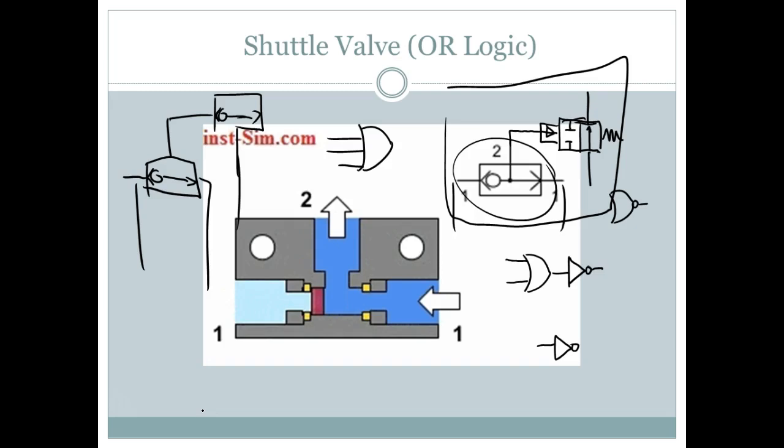No, the flow control is at the cylinder. So if you're going to control the speed of the cylinder, then you would control it at the cylinder. You wouldn't control it at the valve that's actually doing your control. I can show you all kinds of diagrams where they control the flow, and they don't control it at the valve, they control it at the cylinder. That makes sense. So all these guys are just giving me what we call a digital control.